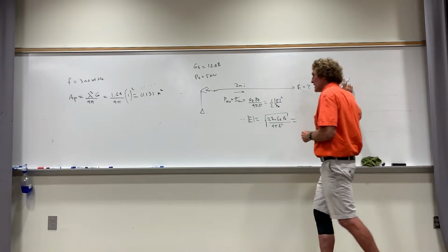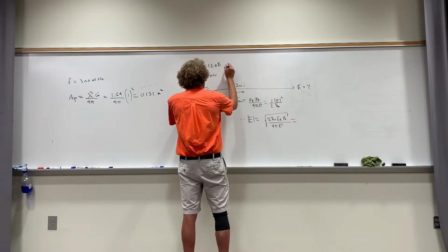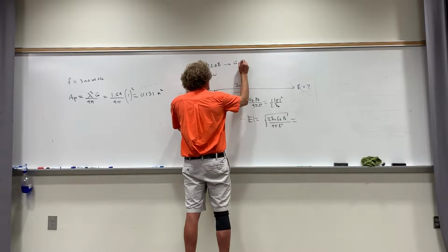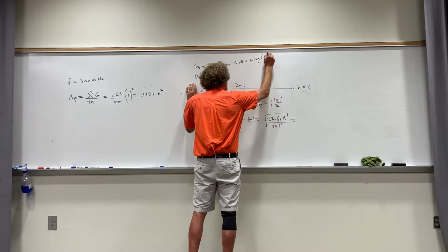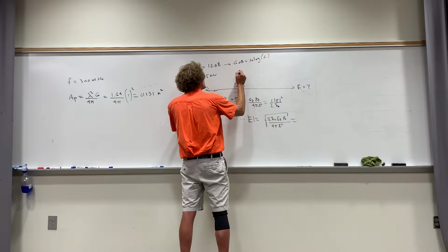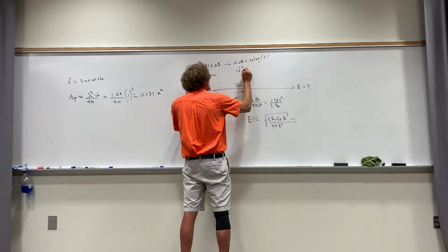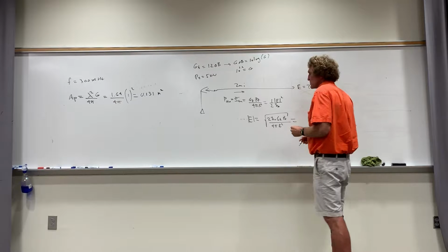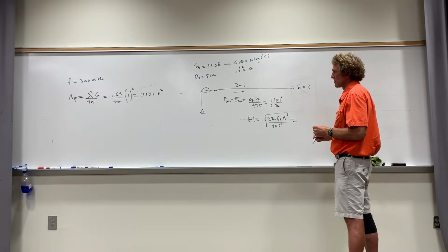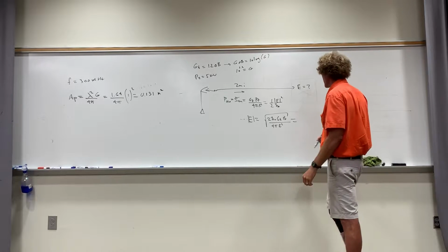Now, to get the gain into a non-dB form, into the linear form, I know that gain in dB is equal to 10 times the log of the linear gain, G, right? So I put 12 divided by 10, or 1.2, and take 10 to that power. 10 to the 1.2 is equal to G. Right? So then you could plug in the numbers, because take a look what you have.